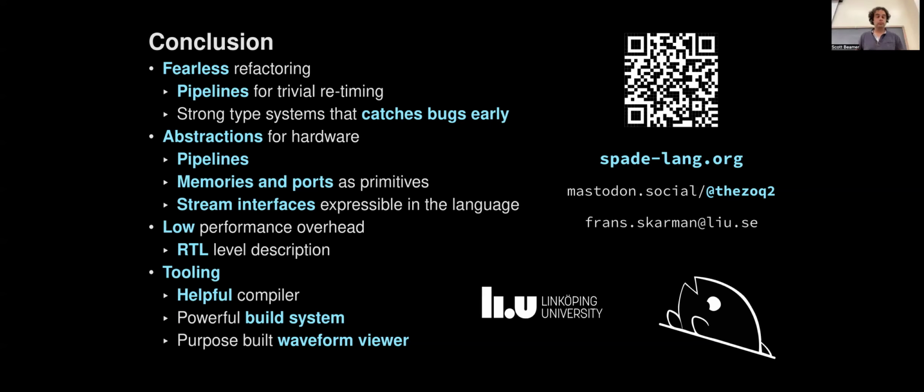And then one other question I had was, does Spade use an IR? Is it tied into CIRCT or FIRRTL or these other hardware intermediate representations? Yeah, good question. At the moment, it's not. The compiler is all internal. I have IRs, of course, because that's how you write a compiler. But at the moment, I have my own backend for emitting Verilog.